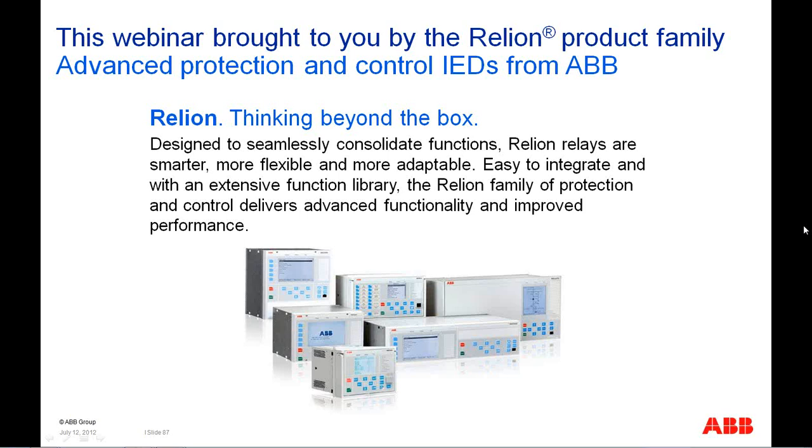We are using an auxiliary transformer on the secondary side of the main CT. Which one needs to be earthed? The main one or the auxiliary CT? I guess I'd have to know how these are connected. Are they connected wye-wye on both sides? If so, then you only need to ground the CT set on the auxiliary. As per the rule, a CT secondary can be earthed only once, in one place. That's correct. You only want to ground it in one place, otherwise you'll get circulating currents and whatnot.